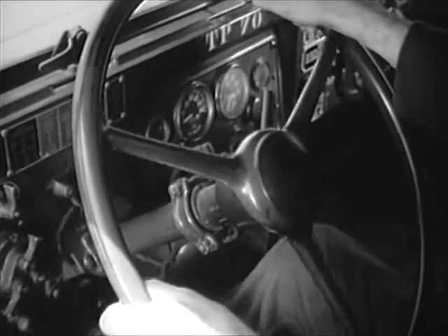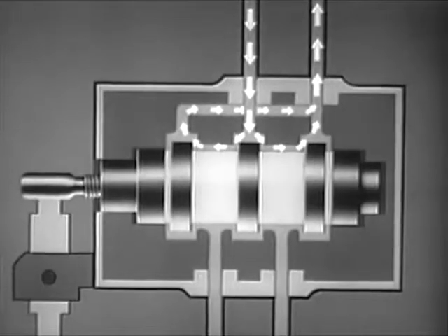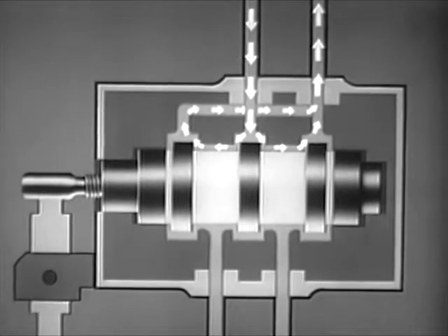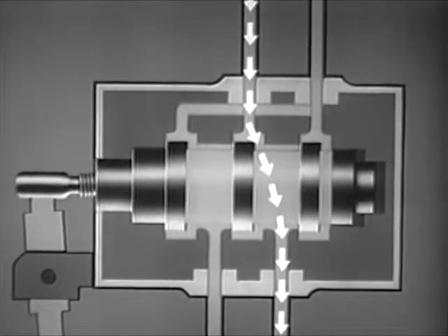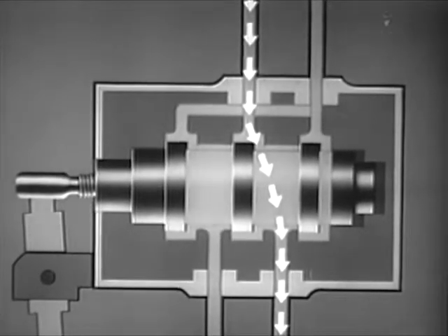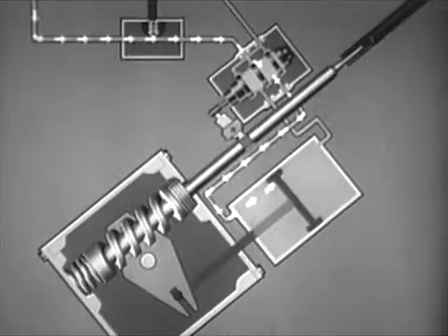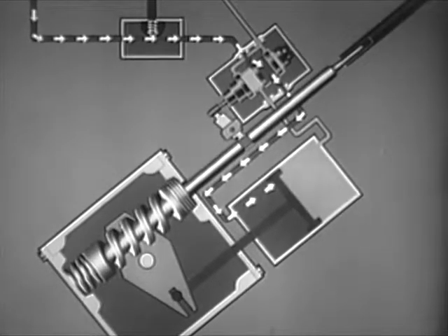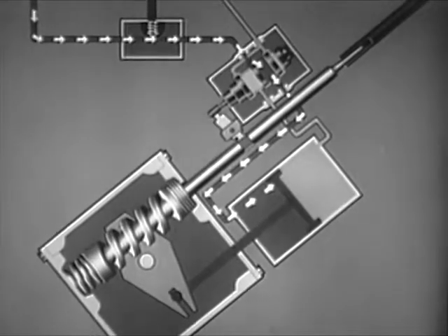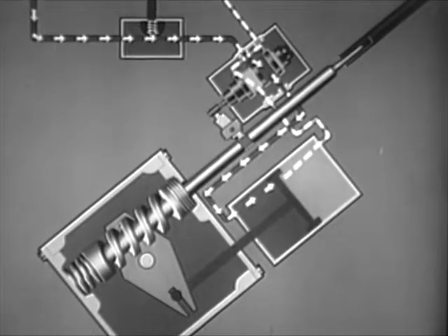As the steering wheel is turned, the up-or-down movement of the cam actuates the control valve lever, shifting the position of the valve spool. The spool lands corresponding to ports on the valve housing direct the flow of fluid from the pump to the power cylinder. This flow of fluid causes an immediate pressure increase on one side of the piston in the power cylinder. At the same time, fluid from the other side of the piston is displaced by pressure differential and forced up and around the unrestricted passageway in the control valve to the outlet port leading back to the reservoir.